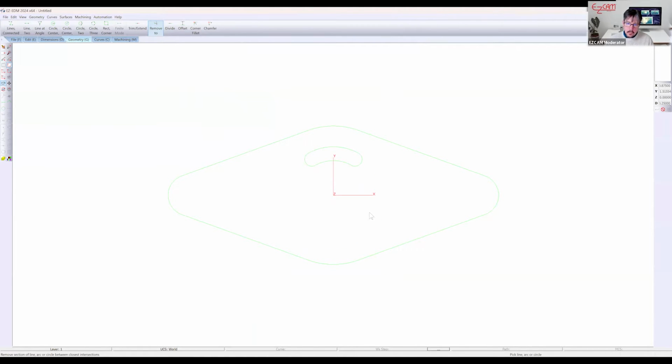I'm going to make copies. I'm going to make 3 copies at 90 degrees. So you go to Edit, Rotate Z, 90 degrees. Make sure I'm off of X, Y, Z, 0. Move over to Copy Mode at the top toolbar. Add our 3 copies, and just put a window around the geometry that we're copying.